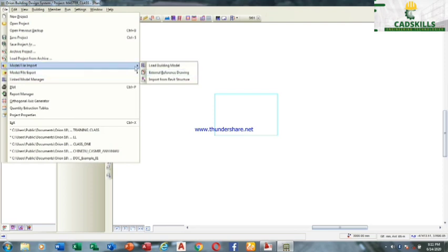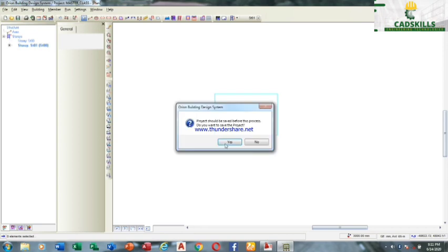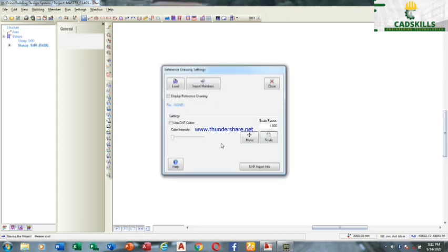The only benefit is that if you are importing from Revit structure, that is supported also with this software, you can go through this place and import it here. You can do your general arrangement and everything in that format and import it here. It's going to work. Okay, so this external reference drawing is already here on the toolbar, so we just make use of this. Once you have started, anything that pops up telling you to save, just say yes, so I can be saving whatever you are doing.